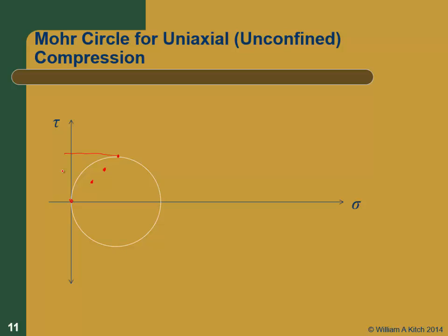So I think this is a thing that confuses a lot of people. And you think, oh, I'm just uniaxial loading. I'm not doing any shear. I'm not putting any shear load on that thing. Well, the load you're applying is a normal load and putting a normal stress. But the state of stress has a significant amount of shear. In fact, that concrete cylinder fails in shear. It's shear that it fails under. It doesn't fail under a normal stress. It may have failed under a normal load, but it's not failing under normal stress. It's failing under shear stress.